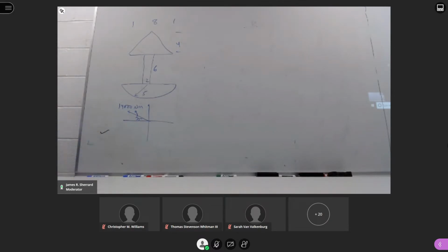I have sketched up on the board what the cross section looks like. And then I've shown the multi-axis bending that we're applying to our system. Okay? So, the first thing I would do is look at this multi-axial bending and break this down into a vector acting in each direction.